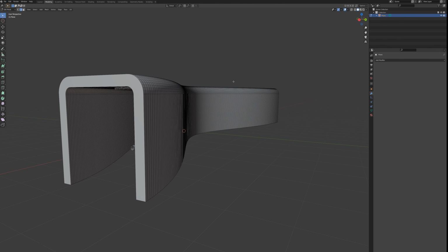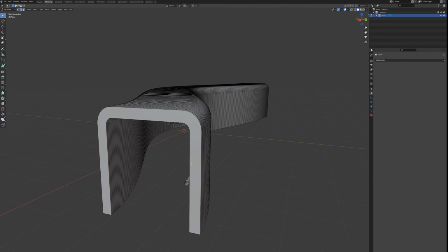The whole tunnel's kind of curvy, and so I want to continue that on this face here. So I'm going to hold Alt and select the whole loop again here. Select this face. Control B to bevel, and let's press C to clamp. Okay, and now this is okay, except for I don't want to bevel those bottom edges.